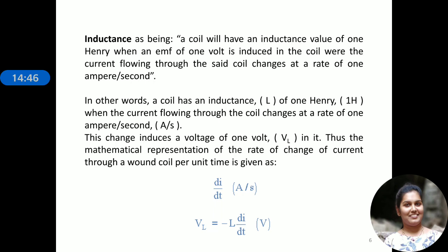and there are many factors which determine the inductance of a coil, such as the shape of the coil, the number of turns of the insulated wire, the number of layers of the wire, the spacing between the turns, the permeability of the core material, the size or the cross sectional area of the core, etc., are some of the points on which the inductance will be dependent. Okay, so all these factors like the size, shape, number of turns, spacing between them, and the permeability of the core material, all together will determine the inductance of the inductor.